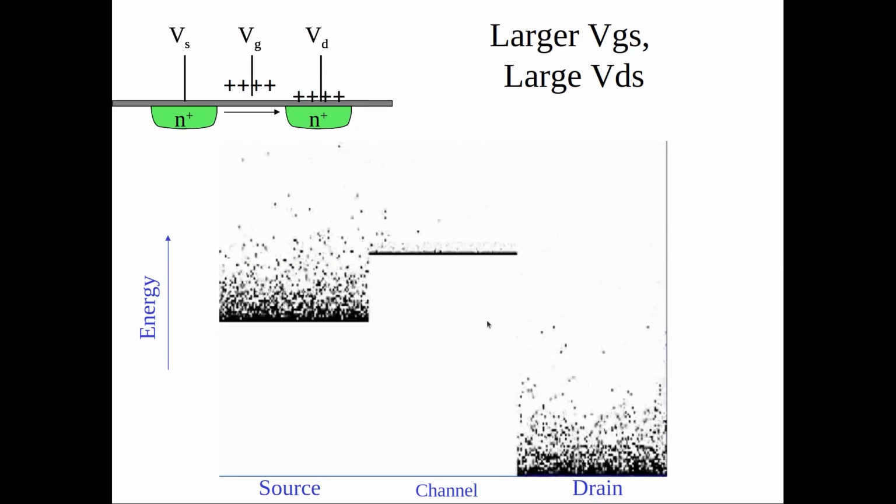And again, this relationship between the energy barrier height, which is proportional to the voltage, and the number of electrons flowing is exponential. And again, it's because of Boltzmann statistics and because of diffusion. We're changing the concentration gradients. And from those equations and the carrier concentrations, those exponentials give rise to an exponential relationship of current, which is basically the flow of electrons. If electrons flow one way, the charge is going in the opposite direction. So current is always flowing in the opposite direction of electrons. That's another convention to remember.